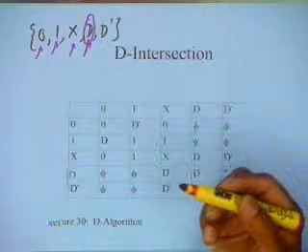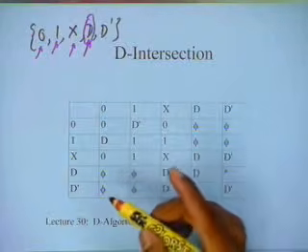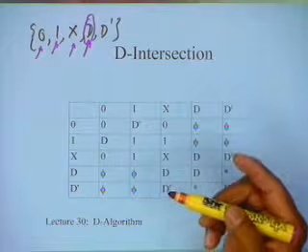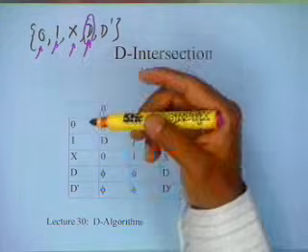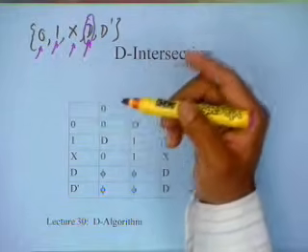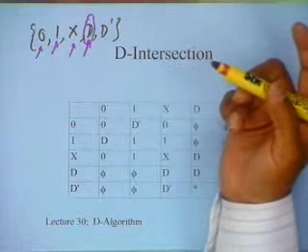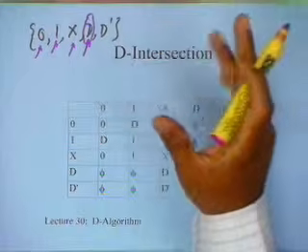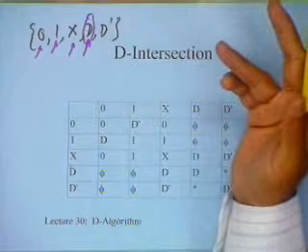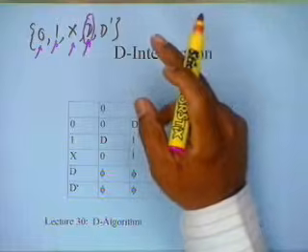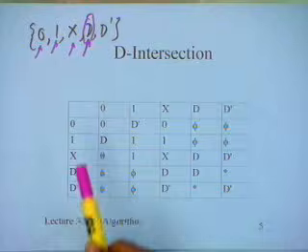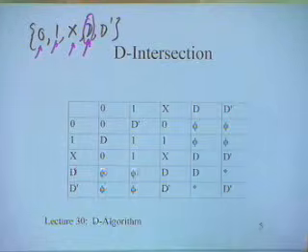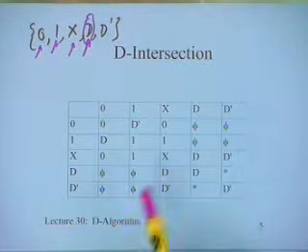D complement is the complement. So, if D is 0 faulty and 1 non-faulty, then D complement is the reverse. There is nothing absolute about it. You can define D in any manner, but you have to be consistent: at one place it is D and at another place it can be D complement, because its behavior is the reverse of the node that is under D. So, however you define D, you have this flexibility, but once you show something to be D, you have to be consistent and call the nodes which are the opposite of it D complement.